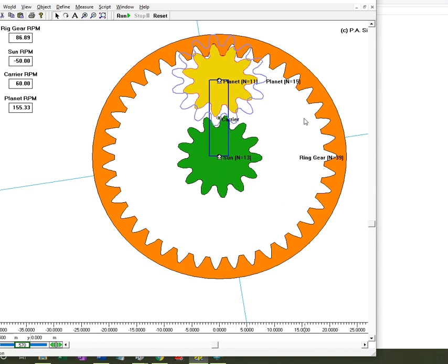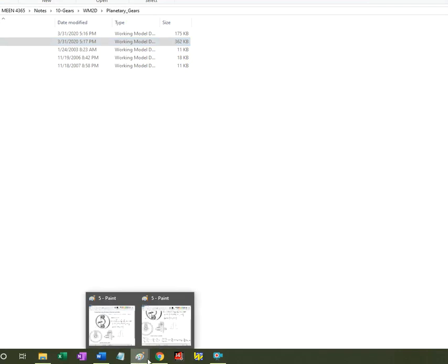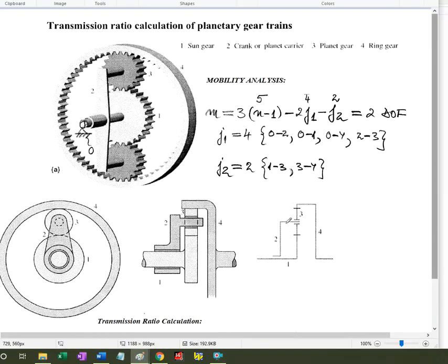All right, so again, fixed axle transmissions, we can analyze for velocity, for transmission ratio. If we do motion inversion, all we need to do is remember that we hypothetically assume an inverted motion equal to negative of omega of the carrier, and make sure you subtract that omega of the carrier when you write the equation. So let's go back to this one.